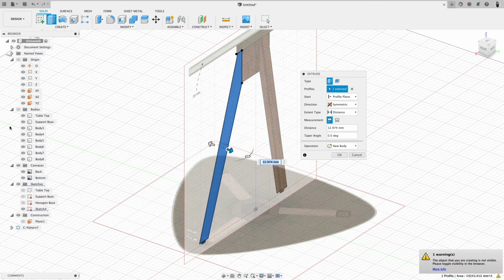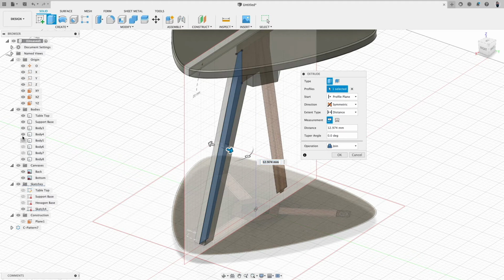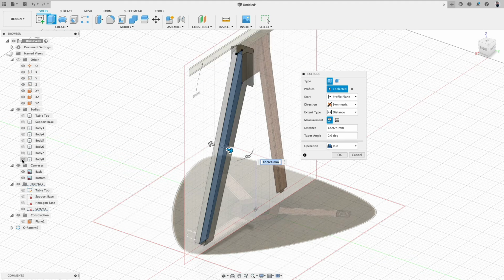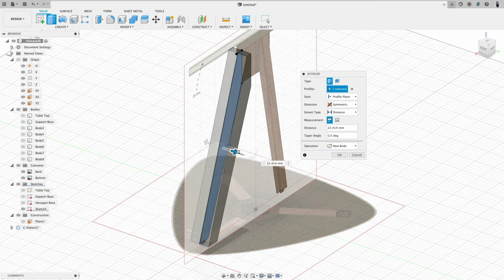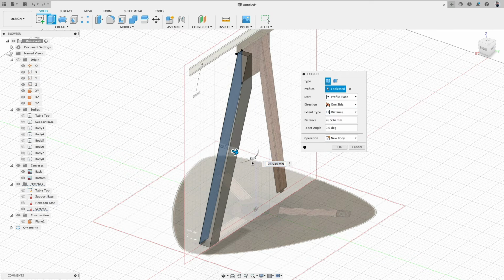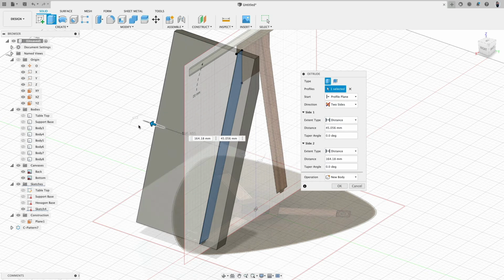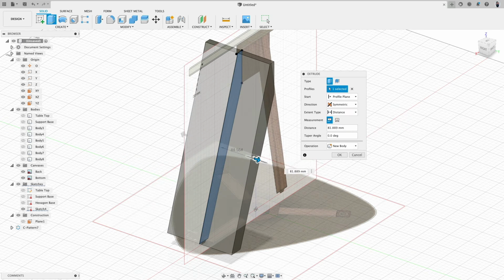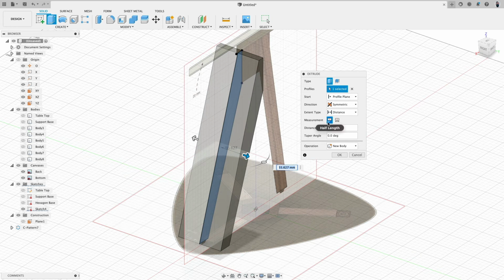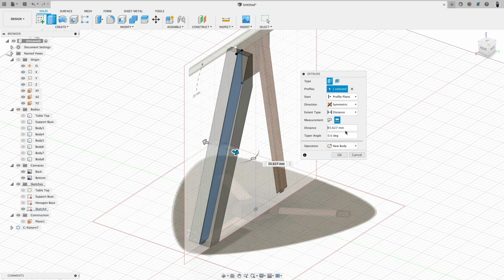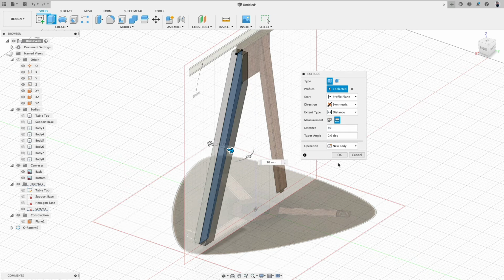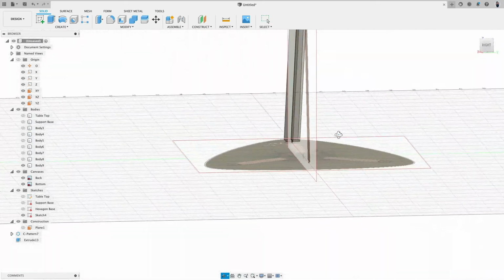And when I push this one out, well, it says, okay, doesn't show the other elements here. There, good, everything is gone. So there I can see now how left and right this goes out. One side only, left or right. Two sides, but individually. Or symmetry. And then here I can specify half the length or the full length. So the full length should be 30 millimeters. Okay, that's it. See, super easy.